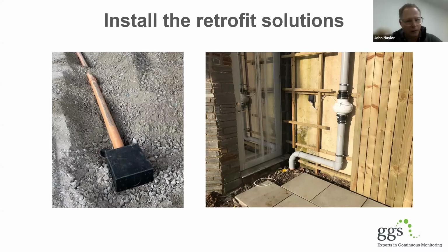And then you can see in the right-hand photograph an actual connected and activated sump system. So that's basically the pipe work and the inline fan that then ejects. It applies suction to that sump box underneath, sucks the radon gas towards that point and ejects it out to air, not near windows and doors, by the way, but usually above eaves and above the roof.